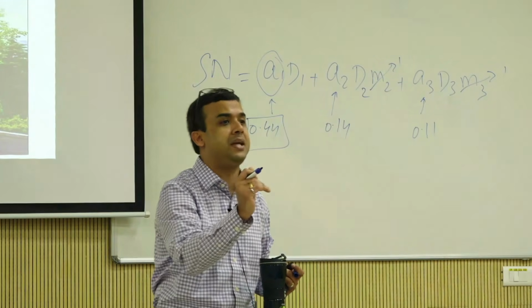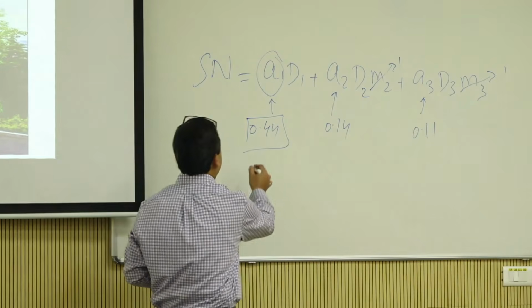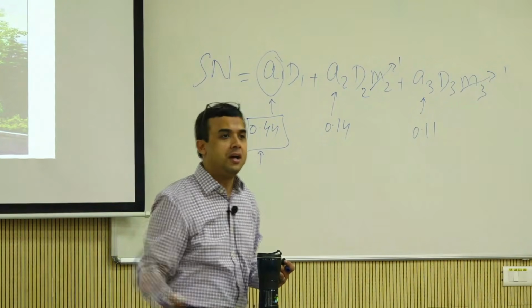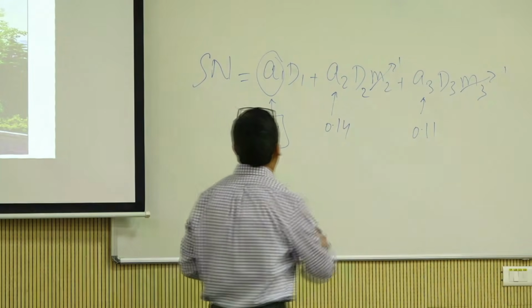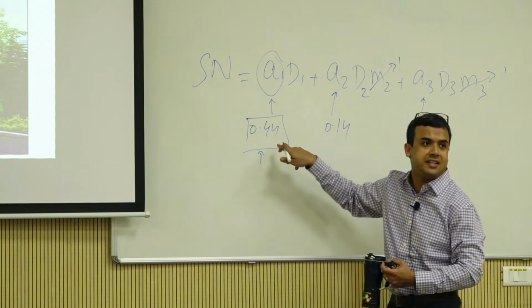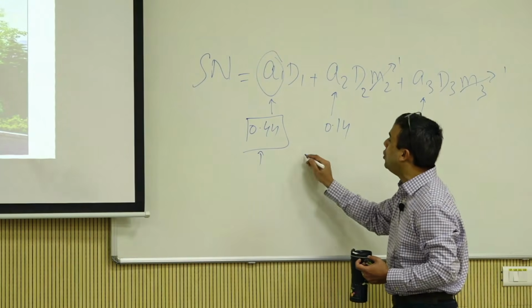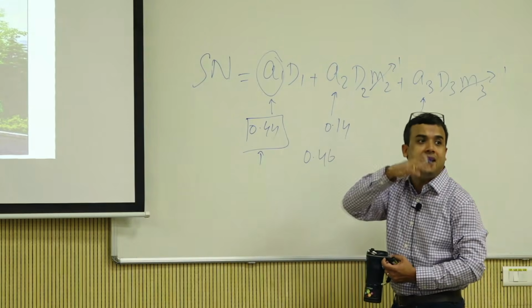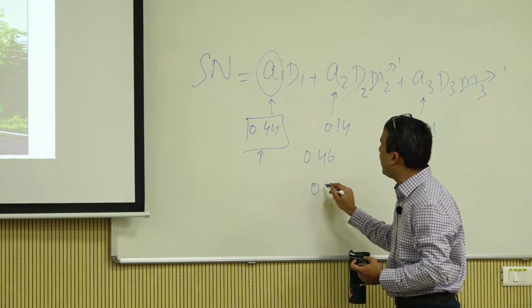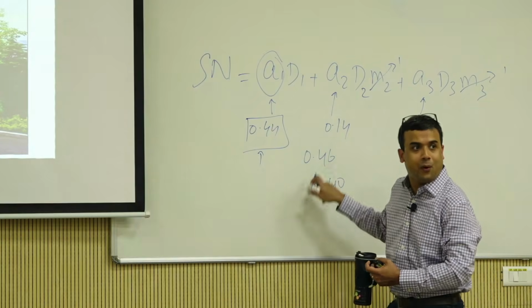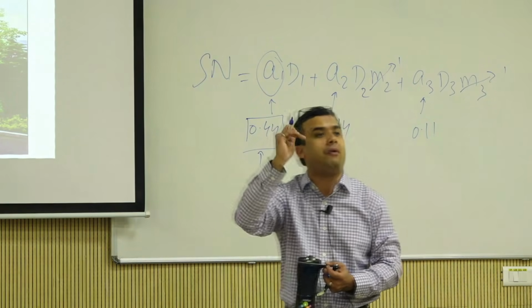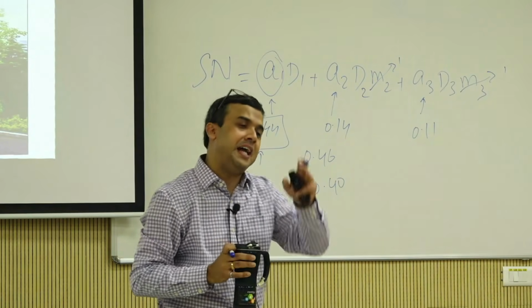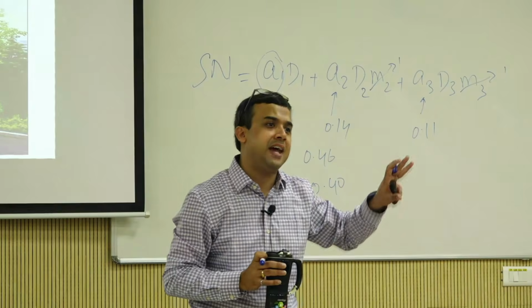How do you have a somewhat improved empirical design? Let's just say 0.44 is the base. Let's just say now in the state of Odisha, you have done so much research and so much data collection. You can say, okay, use 0.44 in this kind of pavement. If I have a really good binder, then maybe use 0.46. If you have a really poor aggregate and everything, maybe make it 0.4. Now what you're doing is building on top of other empirical methods with experience. Do you understand? So that is what the pavement design component is.